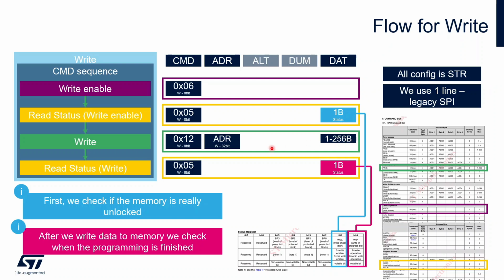So the best way to start is to simply copy the mass erase, and we will change only the command and also add one more feature, because it's possible that the code will want us to program even more than 256. In this case, we need to call this multiple times, so there will be a loop to check if we need to repeat it again and again. But for the first step, I recommend doing it only once to check if you can at least program the address 90 million or 0 in this case.